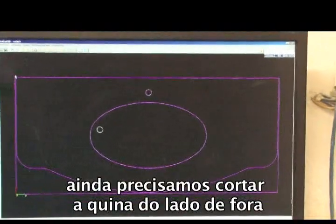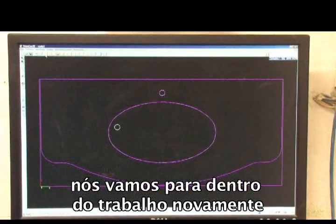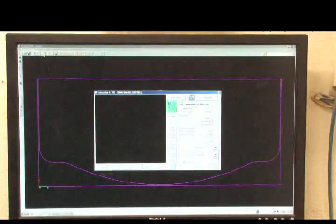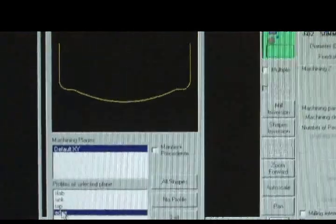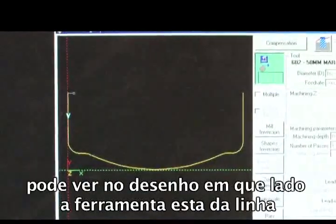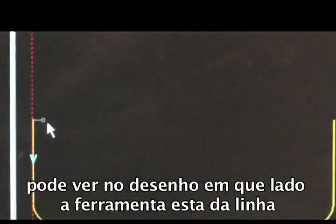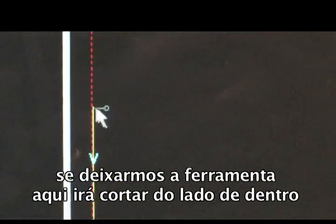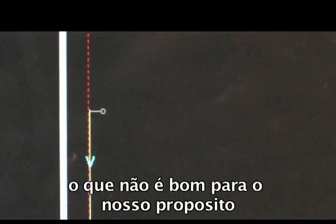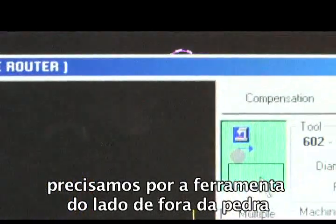We still need though to cut the outside edge, so we go inside again, border or contouring jobs, and we choose the shape, edge, and confirm. Now you can see on the drawing which side the tool is on the line. If we leave the tool here, it will cut on the inside of the line, which is no good for our purpose. We need to put the tool on the outside of the line.